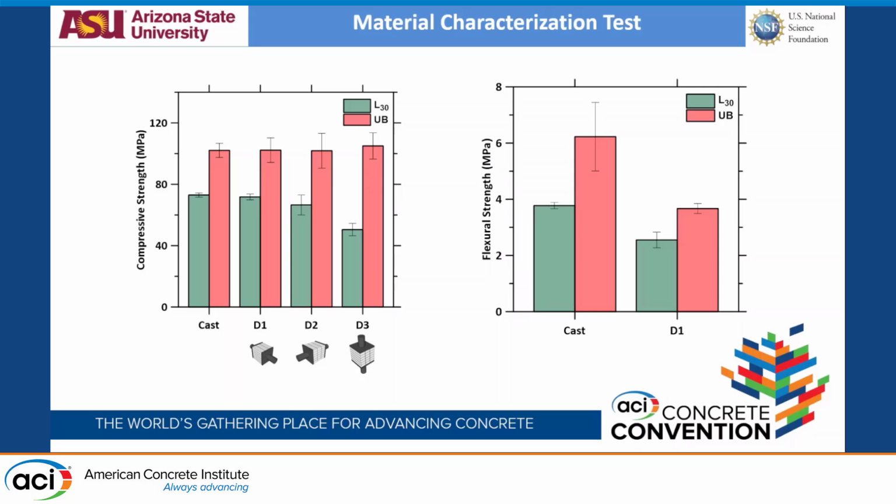Now this UHPC comes as more of a liquid out of the nozzle, and as soon as it sets, it makes a good connection with the filaments, but the next layer that comes above it will always have a delay. It's like you are trying to put a fluid over a solid surface. So the interlayer and interfilament strengths are slightly different in comparison to the L30 mix for the higher cement ratio.